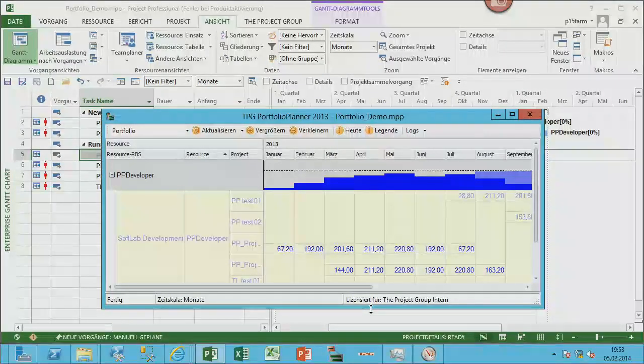These budget resources will be assigned to the project summary task, so to the entire portfolio. And this is the budget limit threshold. We take that to draw the budget limit line, which is here the availability line, and we just run the costs from the several cost types against this budget limit line.